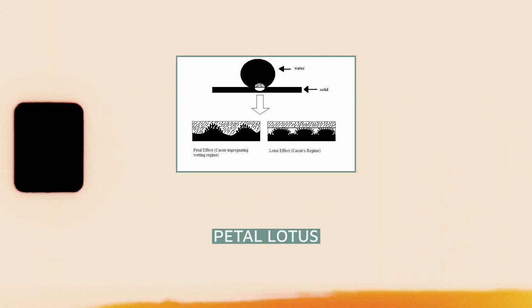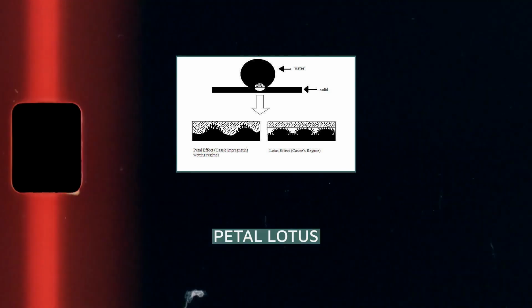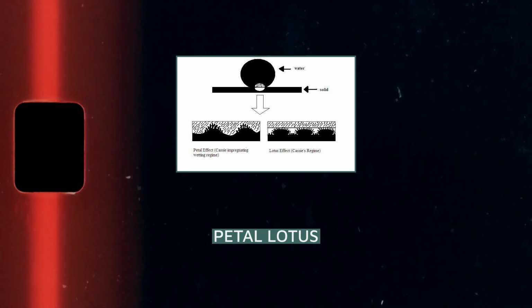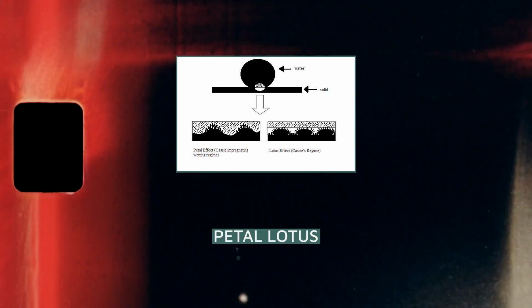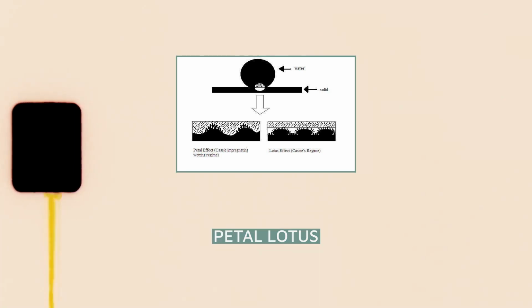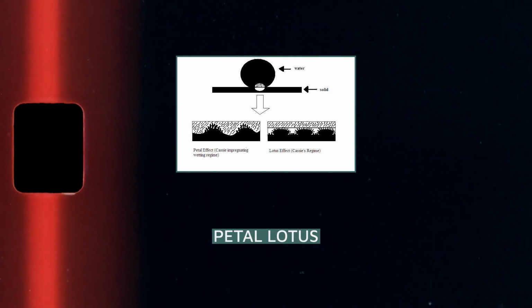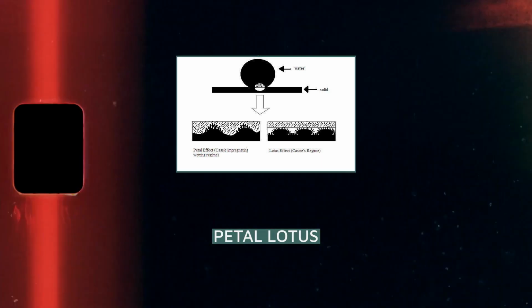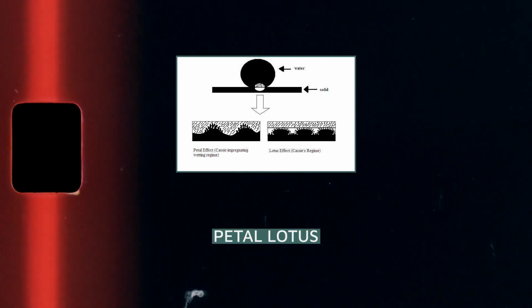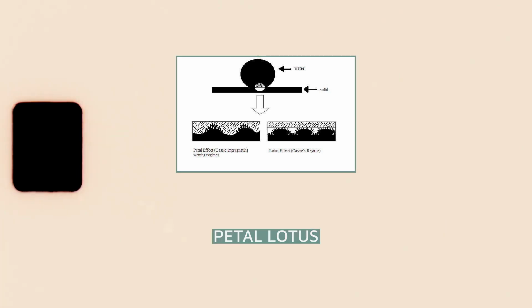A theory that preserves the Cassie-Baxter equation while at the same time explaining the presence of the minimized energy state of the triple line hinges on the idea of a precursor film. This film of submicrometer thickness advances ahead of the motion of the droplet and is found around the triple line. Furthermore, this precursor film allows the triple line to bend and take different conformations that were originally considered unfavorable. This precursor fluid has been observed using environmental scanning electron microscopy (ESEM) in surfaces with pores formed in the bulk. With the introduction of the precursor film concept, the triple line can follow energetically feasible conformations, thereby correctly explaining the Cassie-Baxter model.